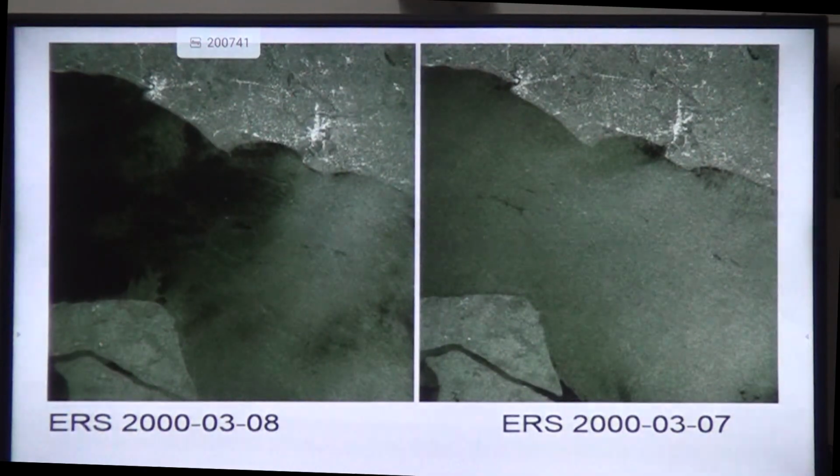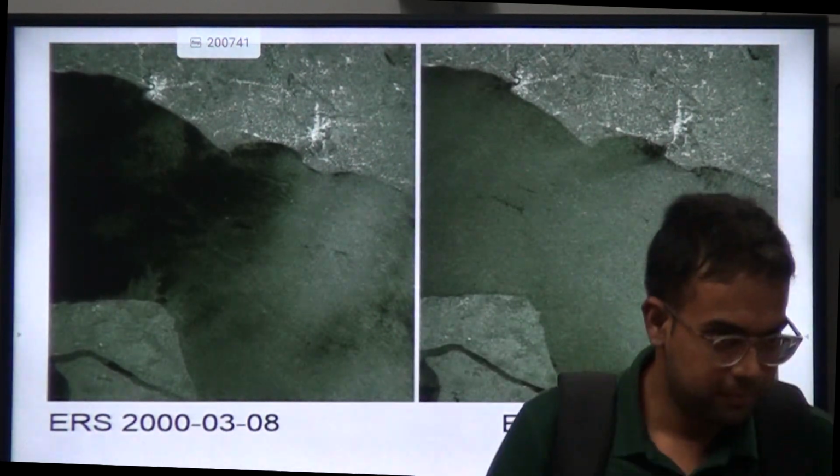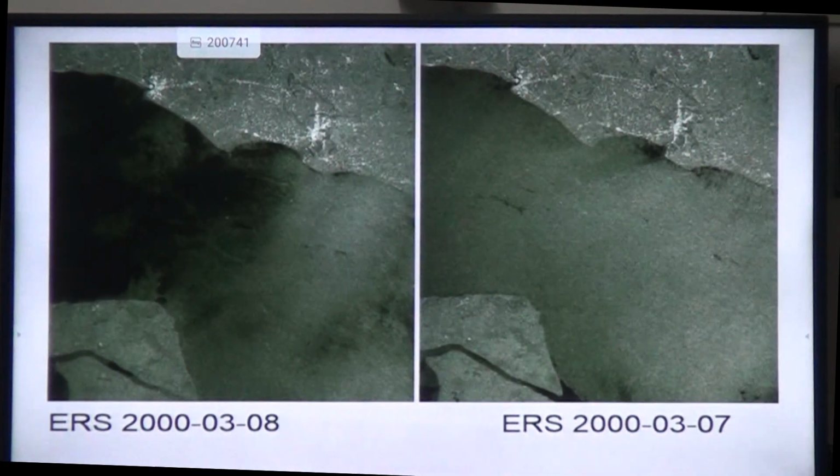Okay, now, see. There is another type of image also that we try to use, that is called ERS, European Remote Sensing Satellite Data as well. Again, not that easy. Some patches maybe can be clearly seen, but the pixel variation gets confused with other types of features as well, depending on the weather conditions and all that. That is why in the first table I showed you what sensors are available for detection of different types of features. Okay, if you take the wrong sensor and try to identify a feature that it is not able to detect, it's a wrong approach.